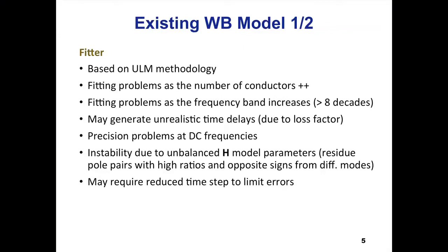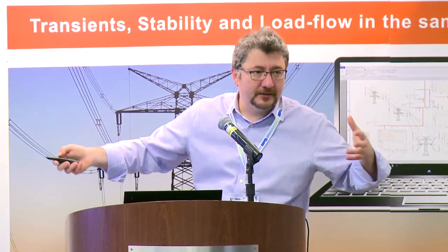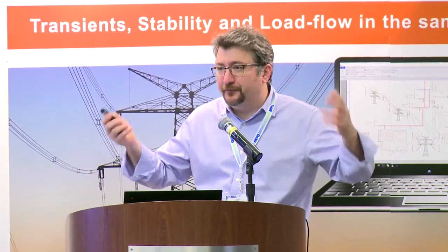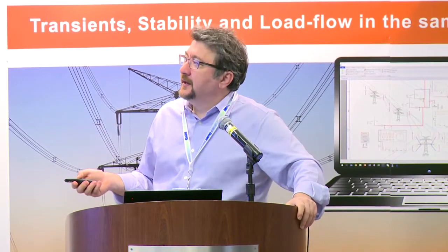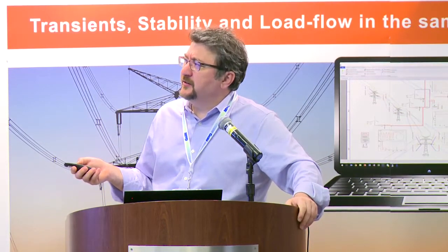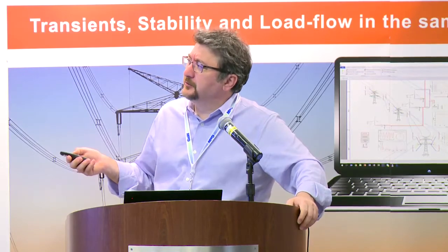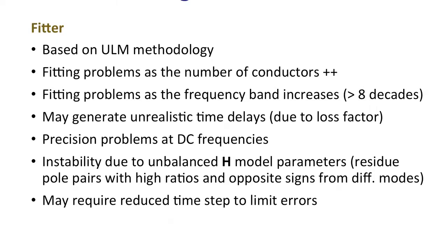Obviously, in the same matrix, you have millihertz and you have megahertz. The conditioning of your matrix is problematic. And sometimes it generates unrealistic time delays. This is due to loss factor in cables. And sometimes you have precision problems at DC frequencies.